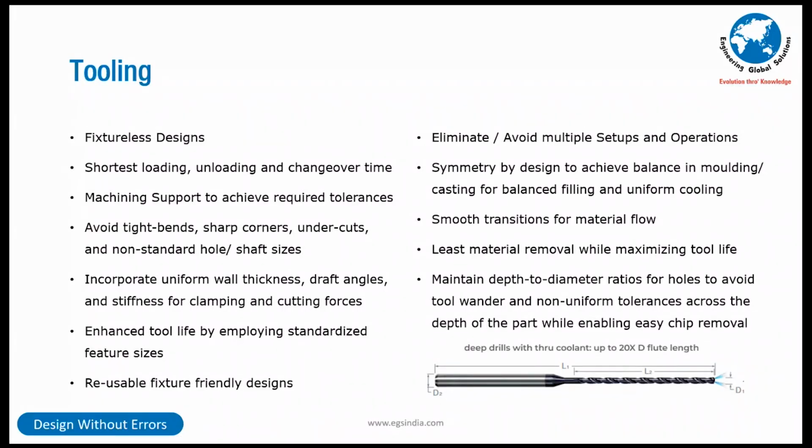Keep it in a library, your Solidworks or whatever CAD you use. Keep all features library, part library, assembly library, and use them. Reusable fixture design, fixture-friendly designs. Already a fixture is available. Why should I make a new one? Design it for that. Eliminate, avoid multiple setups and operations.